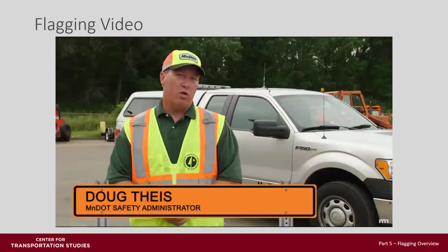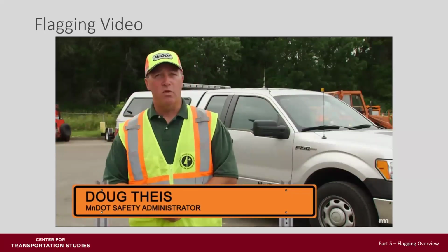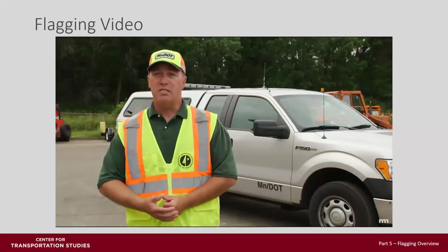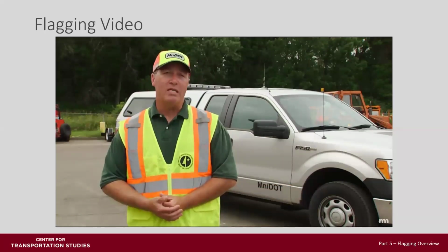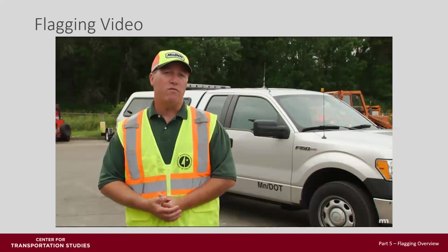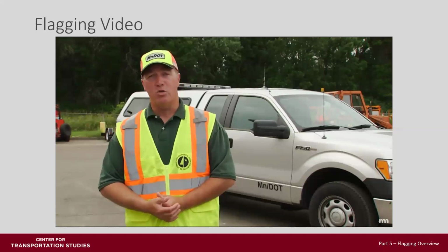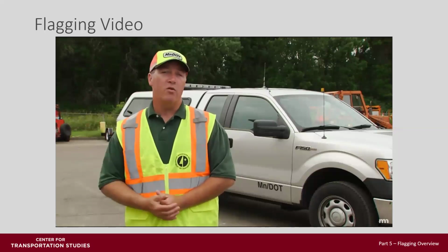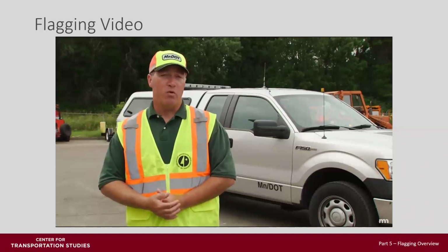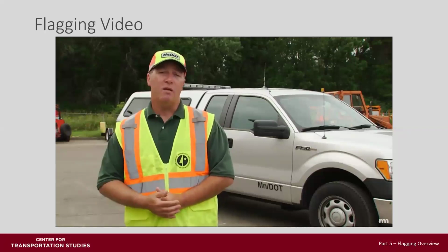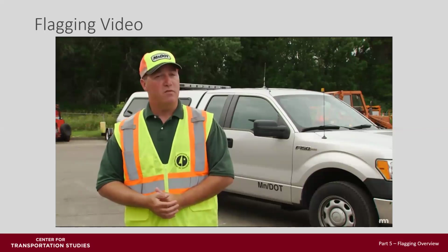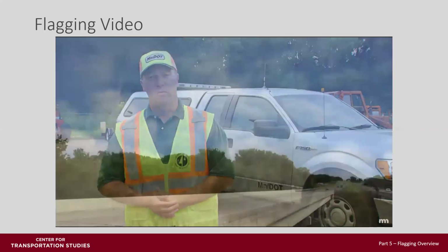As a MnDOT safety administrator, I'm often called to the scene where there's a serious injury or fatality in a work zone. Through years of investigating crashes, I've learned the flagger is a key player in preventing injuries and fatalities in work zones. Flaggers are the first line of defense in preventing vehicles from entering the work zone and for warning others of potential dangers. By preparing yourself with proper personal protective equipment, staying attentive at all times, and never turning your back on traffic, you can prevent serious injuries and fatalities from occurring in the work zone.